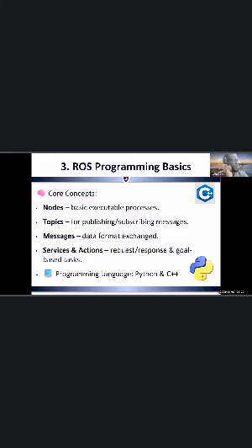All right, so topics. Topics are basically what we use to communicate between nodes, right? Now I have explained what nodes are, so now we have topics. When we say topics, we have publishers and subscribers. A particular node can have a publishing topic. You can also remap it to become another type of topic. Topics are basically tags for a particular node. For example, a popular topic in ROS for LiDARs is slash scan, right?